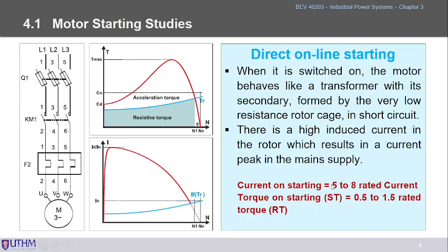We start from the DOL, the direct online starting. As implied by the name, direct online means we start our motor, especially the induction motor, directly. That means we have the switch here, so we just switch on the switch directly to this motor, and we start it. That means we start this motor using full voltage starting. Once we switch on the switch to run the motor, this motor will receive full voltage at the beginning of its starting.